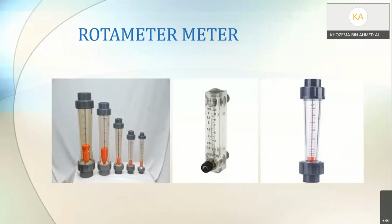You can also see different shapes of floats. The way you read it, this one is usually for a liquid, and this one is usually for a gas. You can see the scale here. If your float is around this point, this is the value of your flow rate.